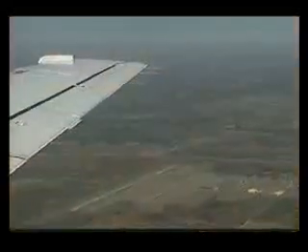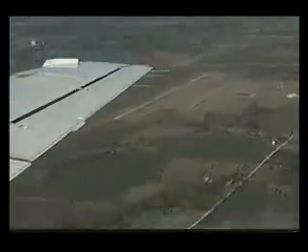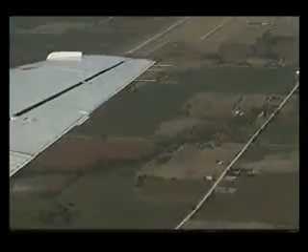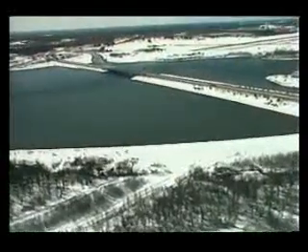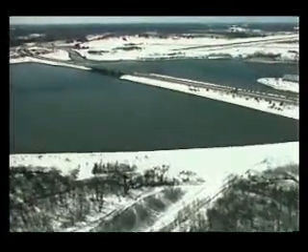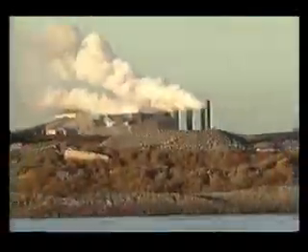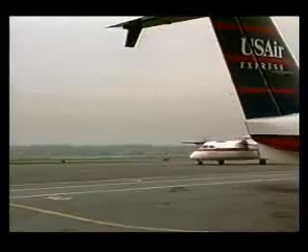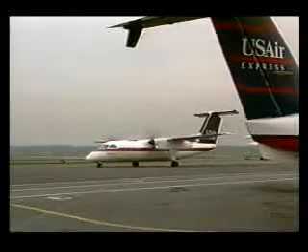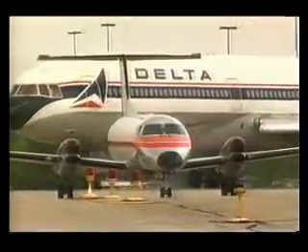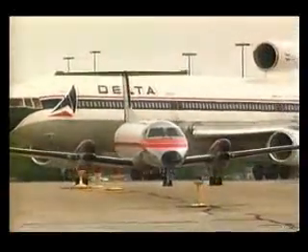The very nature of commuter airline operations subjects your aircraft to more corrosive environments than the larger aircraft. This is because commuter aircraft generally fly at altitudes lower than 20,000 feet, which exposes them for longer periods of time to the worst operating environments, from acid rain to saltwater spray. Also, due to the shorter flights and longer utilization times of commuter aircraft, they generally go through more operating cycles than a major carrier, which contributes to corrosion fatigue.